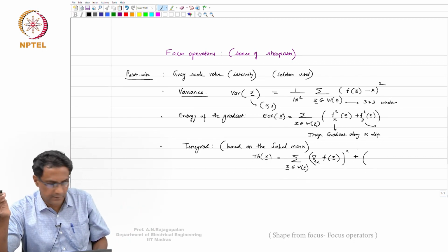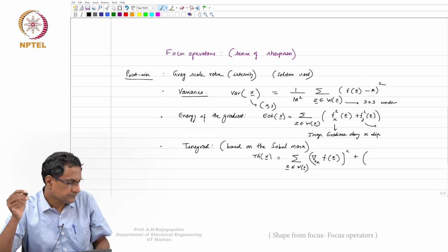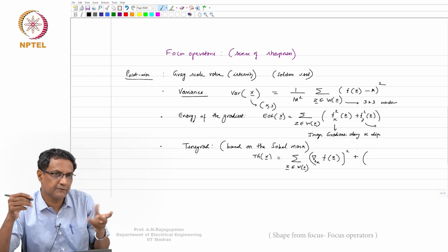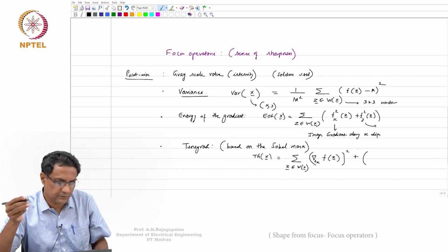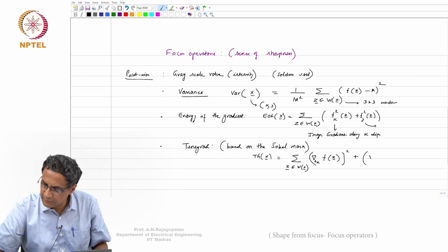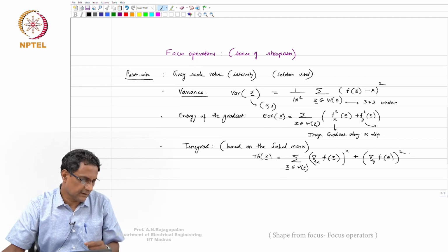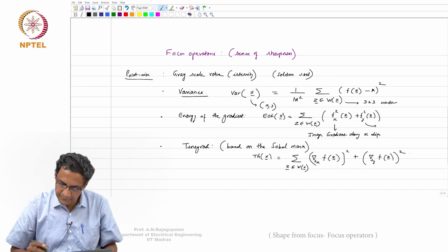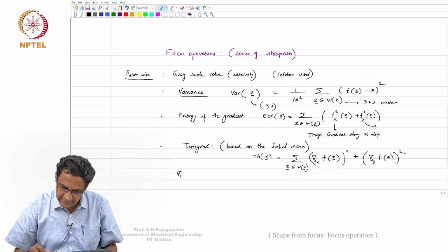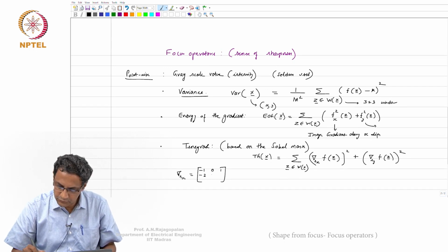Sobel mask is supposed to be better because it tends to add a kind of weightage when you do this sort of differencing. That is why none of these may really matter so much, because at the end of the day, it is the image quality or the underlying image activity that will actually decide. But this Sx will be a kernel like this: -1, 0, 1, -2, 0, 2, -1, 0, 1.